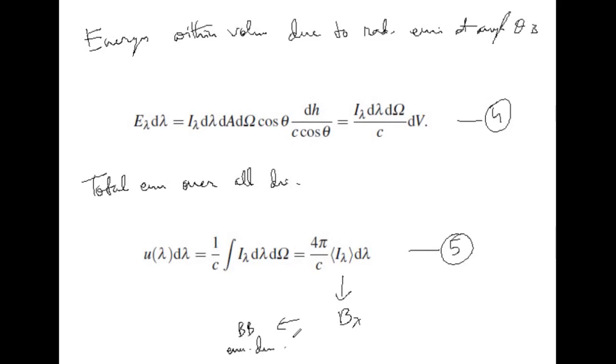Fine. Now what next? Well, you see, we already know that the pressure on a mathematical surface is related to the flow of momentum through that surface. We can understand this by imagining that the mathematical surface is replaced by a real solid surface, and the momentum that would normally flow through the surface must now bounce off of it, reversing direction in the component normal to the surface.